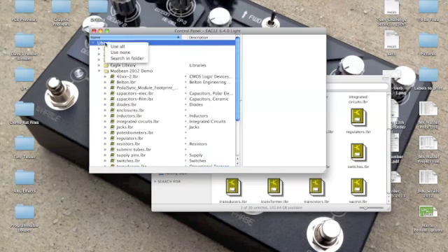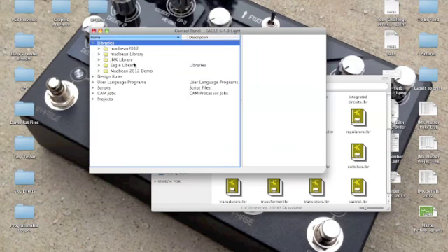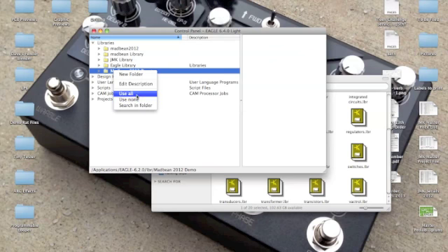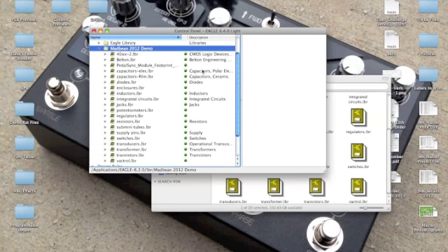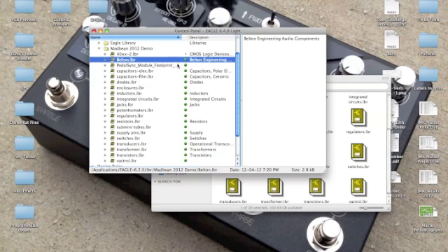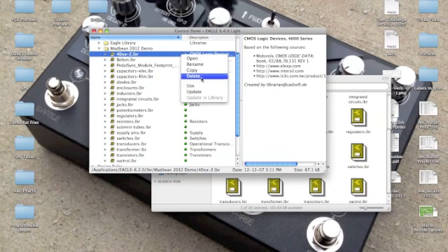If we were to use none, that's another thing I should show you about how to control which library you're currently using. You right click on the libraries and press use none, and then you can find a library you want to use, right click and say use all. Notice here now all these little green dot lights come up. That means it's being used. You can also choose an individual part and say don't use. See that? Use. Right? And then you can turn it back on again.